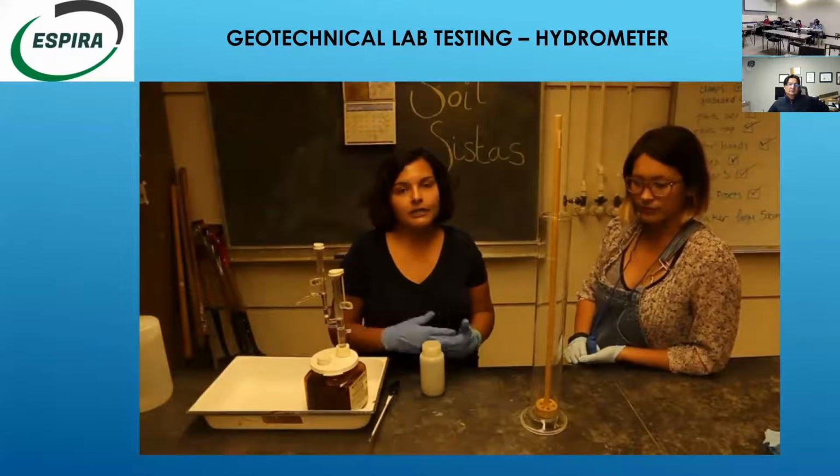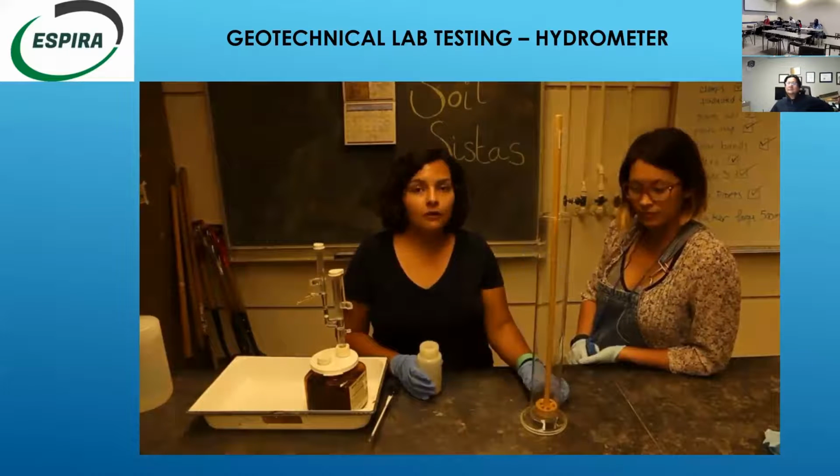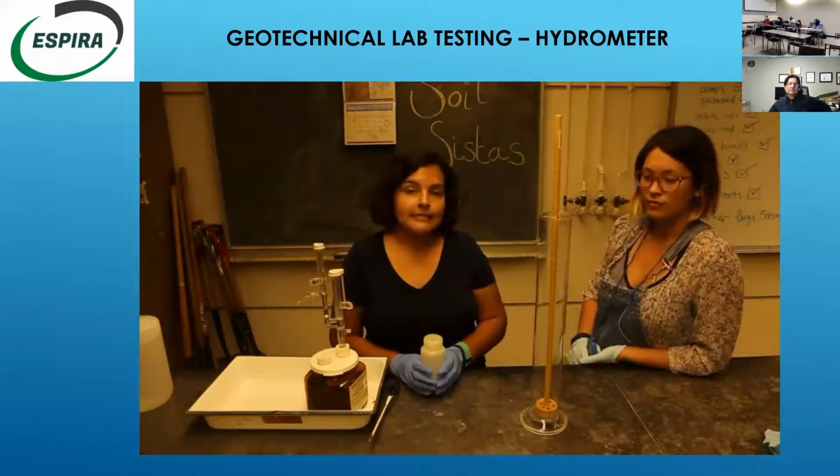Sodium hexametaphosphate acts as a deflocculant, so it breaks up those soil aggregates so the sand, the silt, and the clay aren't bound to each other in aggregate form. That way we can get more accurate readings in our sedimentation jar, because if they are aggregated, things will settle out faster than we want them to. So we really want to coat all of the soil particles with SHMP.